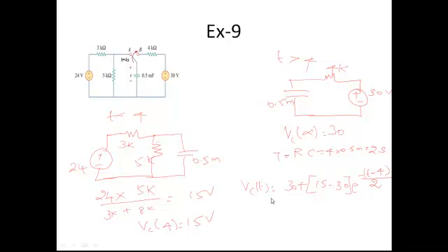Now students, I have given you some simple examples and some examples which cover the entire thing with respect to RC. In my next video, I will give you the lecture on RL, with similar problems, but the approach will be very similar. What you need to understand is whenever RC is given, your first target is to find the voltage across the capacitance. From there you can find the current through the capacitance or through any other element, or the voltage across any other element.